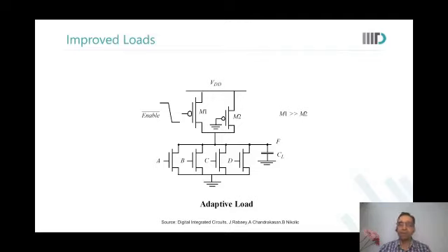No, and Deepank. Step back. This is a NOR gate, a 4-input NOR gate. If you have to make the control of this PMOS based on the inputs itself, then you are actually going for a static CMOS implementation, aren't you? Right. You will have to put a gate to generate the enable signal now. Okay. The entire effort is to save area. Right.